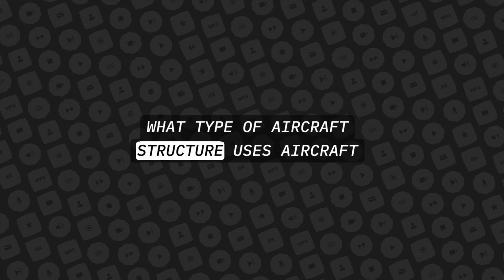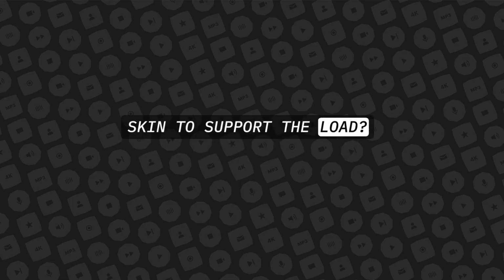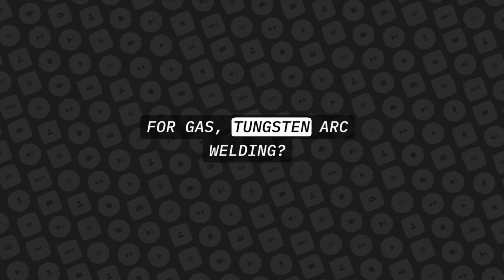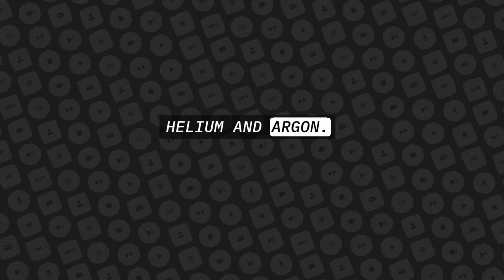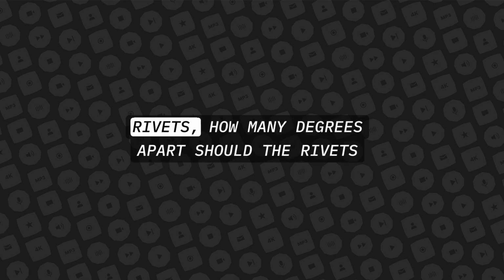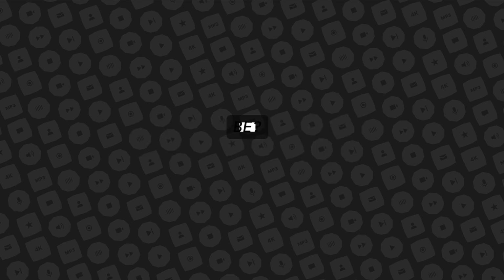What type of aircraft structure uses aircraft skin to support the load? Monocoque. What type of shielding gases are used for gas tungsten arc welding? Helium and argon. If you do a circle sheet metal patch with 8 rivets, how many degrees apart should the rivets be?